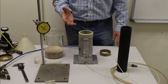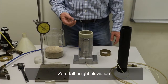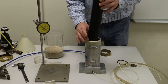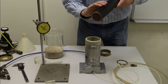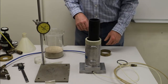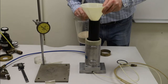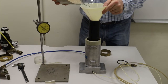For this specimen, we want to make it as loose as we can, reasonably. So we're going to use a technique called zero fall height pluviation. Essentially what we're going to do is use a cylinder that's slightly smaller than the specimen, that has a screened opening on the bottom. We're going to place that all the way down to the bottom of the cap there before we start. We're going to take our sand. We'll have weighed the mass of this sand first. And we're going to pour the sand into that inner cylinder.